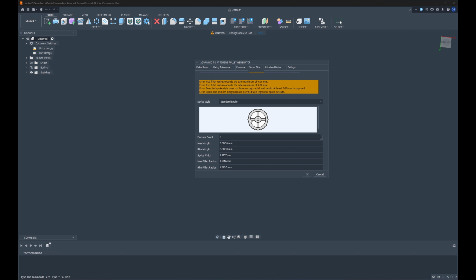So if I go to the tab, I can either get rid of the spoke or try to adjust things like this one to see if it helps. Sometimes there is no single cause, depending on the error. In this case, the problem, or one of the issues here, is that the depth is not enough, and that's purely because of the ridiculously high diameter I've set here.